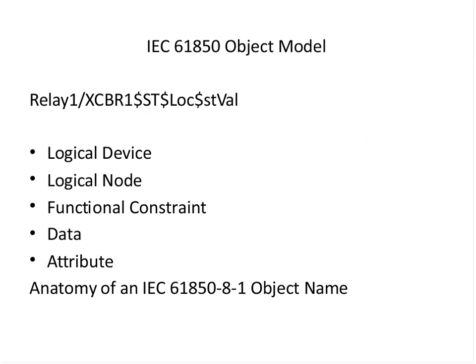Now I'm going to show you how beautiful 61850 is. 61850 has a concept of a logical device, in this case a relay, and then a logical node, in this case a circuit breaker, and then it has a functional constraint. This ST stands for status, and then there is LOC, which means that the status is local as opposed to remote or some other location, and then there's an attribute, the data, and then there's a value associated with it. So it's hierarchical. Notice the hierarchy in it.